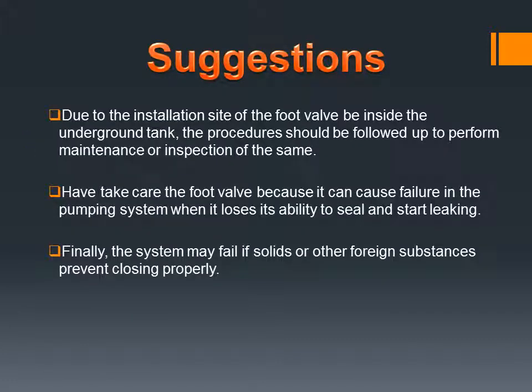Suggestions: due to the installation site of the foot valves being inside the underwater tank, the producer's instructions should be followed when performing maintenance or inspection. Take care of the foot valves because failure can occur in pumped systems when the valve loses its ability to seal and starts leaking. Finally, the systems may fail if solid or other foreign substances prevent it from closing properly.